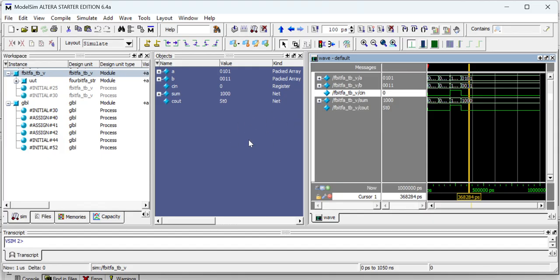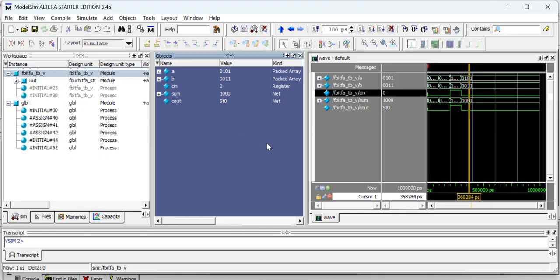Now I hope you completely understood the test bench. Why are we writing the test bench? In order to verify the functionality of your design. For that we have to write a top-level test bench, a stimulus block, under which you instantiate the design block, then drive the input signals with stimulus, check the results and display them. Both the design block and stimulus block are simulated and the output waveform result is verified. I hope you understood everything. Kindly explore the design block and the stimulus block test bench for the next experiment, the multiplexer.